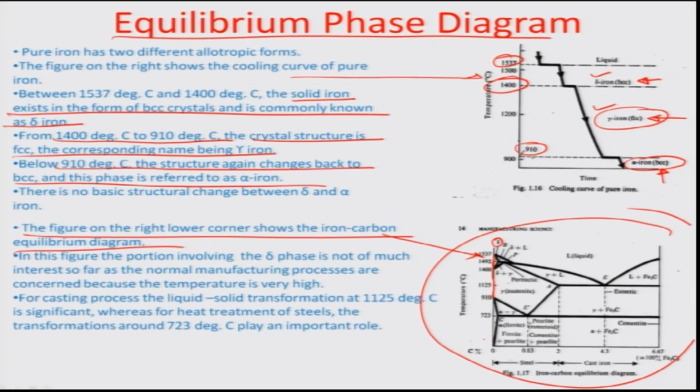So, you have three different structural constitutions of the iron, and then obviously you have a dissolvability of carbon varying between 0 to 6.67% right here, where in one case it is complete cementite, Fe3C, 100%, and the other case this corresponds to only 6.67%, beyond which the iron cannot dissolve the carbon. So, below this there are different phases. In one half, the strength of the iron increases very highly up to 2%, and beyond 2 and below 6.67, this is actually the cast iron phase.